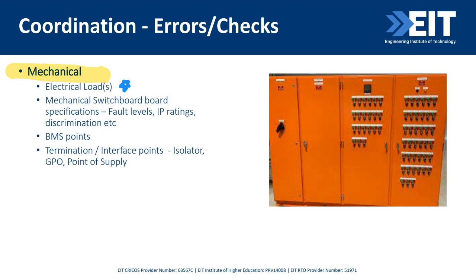Other things we need to check is their switchboard design. Because we are supplying power to their mechanical switchboards, we need to tell them what their fault level could be because it's based on the supply upstream.